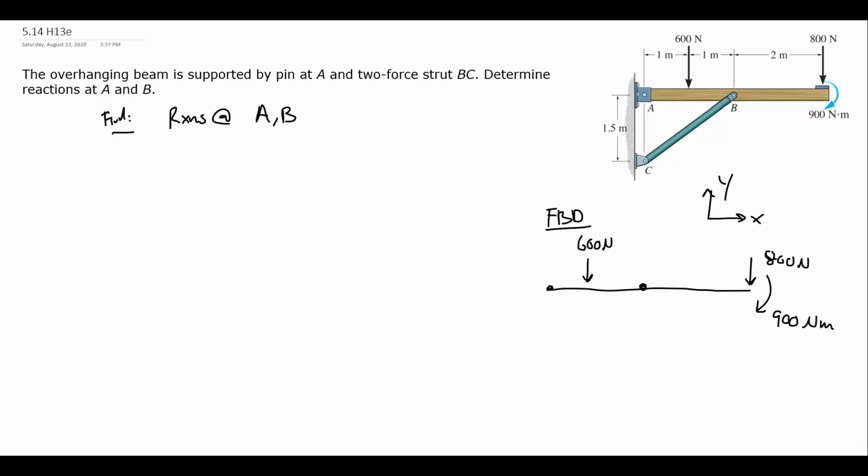And I'll need to start to put some dimensions down. So that's going to be 1 meter, and 2 meters to go from A to B to the end there. So I've accounted for all of the applied forces. Now I can put in my reaction forces. So I'll start at A.